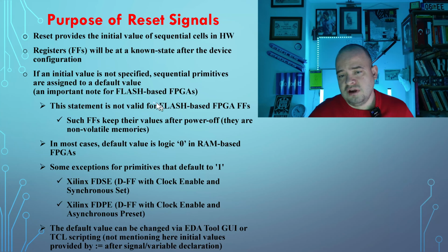But as you know, flash-based ones do not require a configuration flash externally. So unless you force a bit stream load from scratch after a new power on, they will keep their previous values. So this is the behavior of flash-based FPGAs. You can test it in your lab.